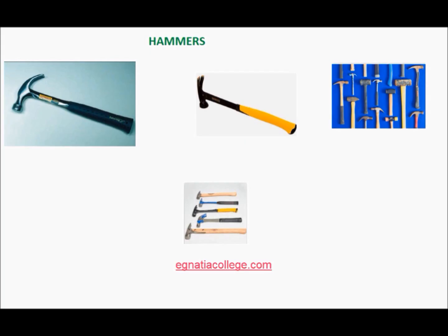Hammers. Numerous hammer types are available, with different heads, claws, and weights. A plumber uses a hammer mostly for removing nails and installing wood bracing, pipe supports, and pipe protection shields. Focusing on the weight or the head type or on the type of claw is not as important because plumbers use hammers less often than carpenters. When removing nails from a wooden structure to allow for holes to be drilled, a straight claw works better than a curved claw hammer.